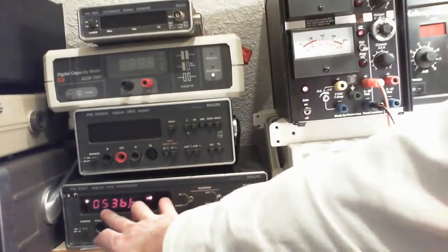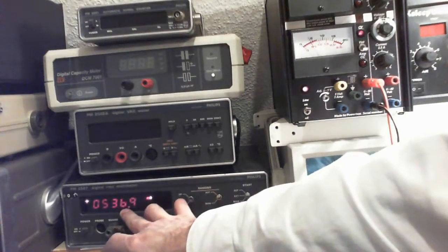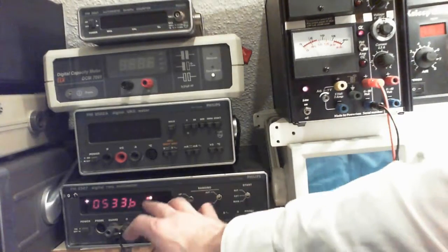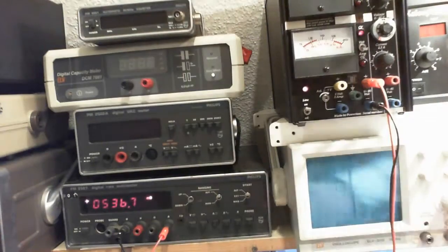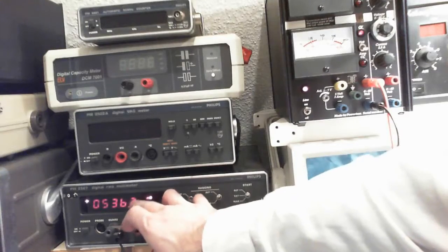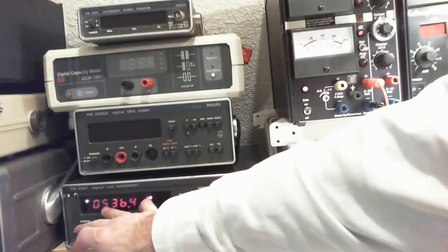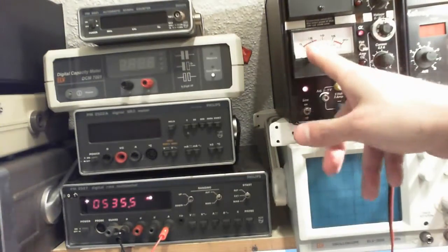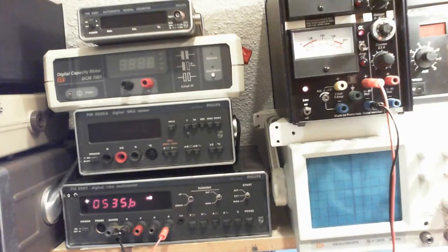And you can see that I'm reading 537, 535 milliamps here, which, if you multiply this by 10 raised to the power negative 3, becomes 0.536 amps, for example, which is what we are reading here. So that's basically how you do a current measurement here. And now let me show you this down here as well.